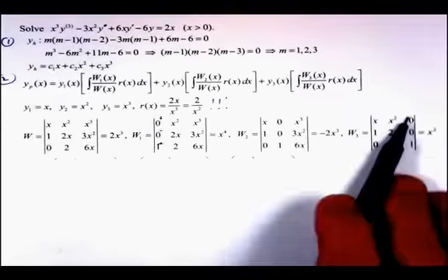We have a beam of some length L, and we're going to call downwards y, and along this way will be x. Okay? And we're only going to think of a two-dimensional flexing. And so downwards positive, the further it flexes downwards, the bigger y will be. So it's a bit like the mass on the spring, where downwards was counted as positive as well. And so when you load that beam, this beam is clearly being supported at one end or the other, so it hasn't moved. But when you load the beam, it tends to flex in the middle. And so the assumption that we're going to build into this is that it is not flexing too far. Because obviously if you flex it too far, there will be a stage where it breaks.